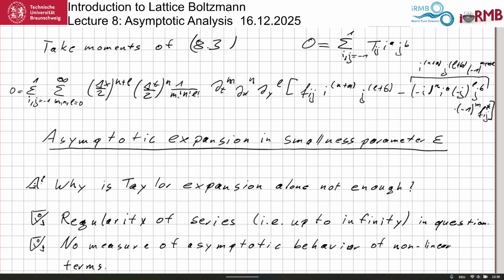But one thing you have to remind yourself when you're in fluid mechanics: 99% of all of these things disappear and don't work. Even linearization, if you think about it, you have a Reynolds number, which is the ratio between the nonlinear part and the linear part, advection versus diffusion. Once this is larger than 1, it means the nonlinearity is stronger than the linearity. And usually we have Reynolds numbers in the billions.